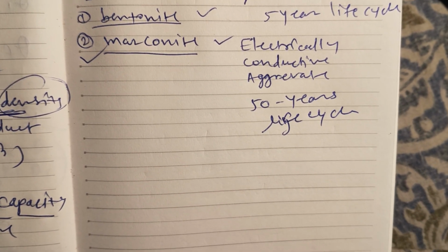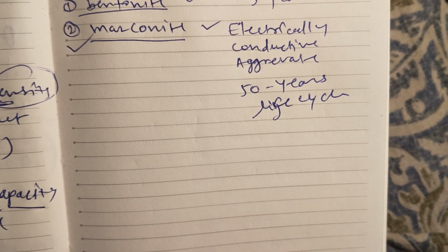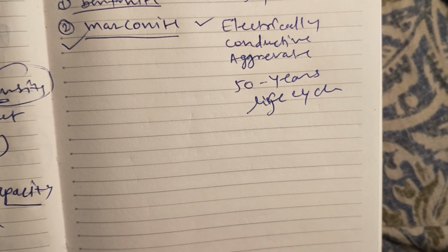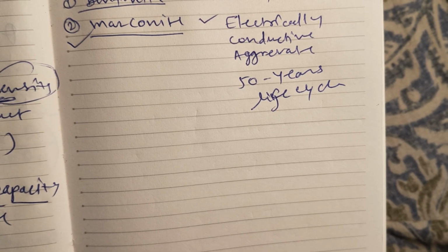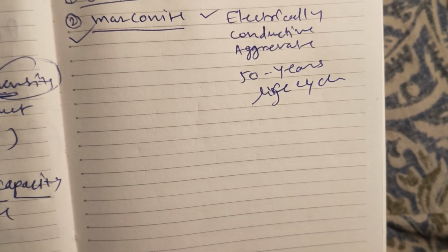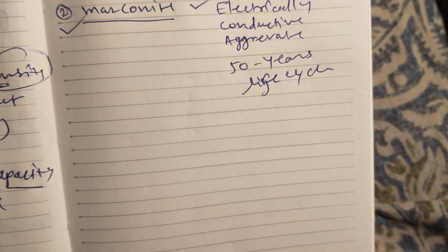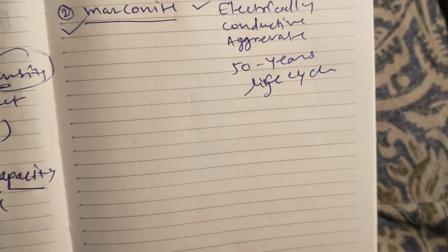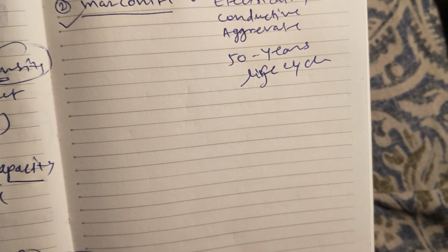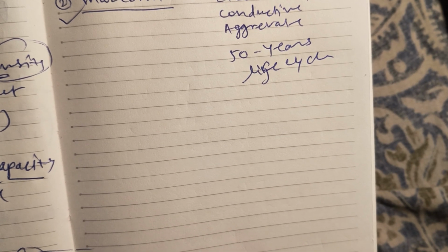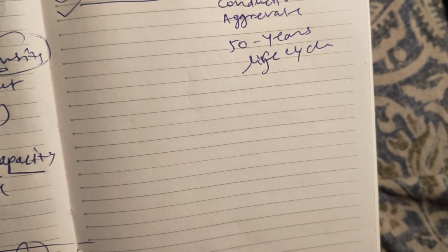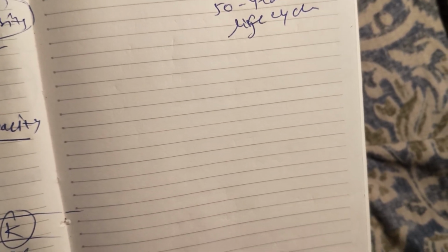In the past, engineers relied on technology related to generally available minerals to design the earthing system for various applications like power stations, buildings, railways, industries, complexes, water and gas plants. These earthing systems require the presence of water to maintain moisture and earthing resistance. In the 19th century, marconite was specially developed to meet the requirements of these earthing applications, but without the need of water. It is an electrically conductive black granule used as a backfill material to enhance the effectiveness of the earth to achieve durable, stable and low resistance performance.